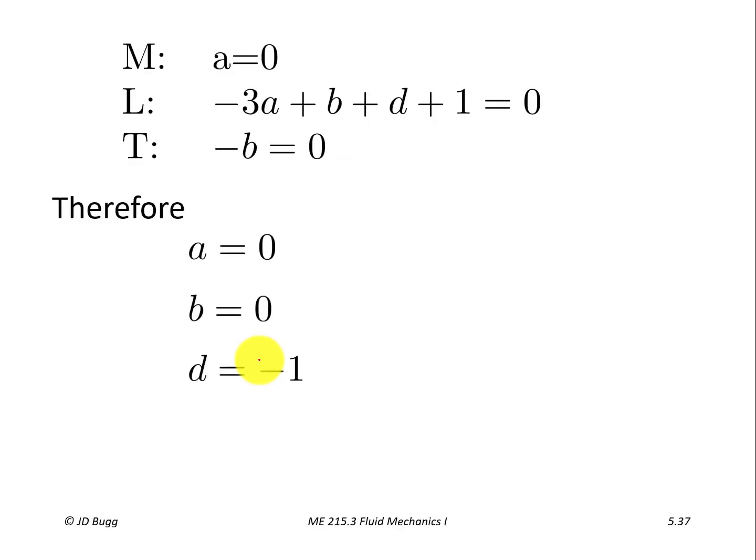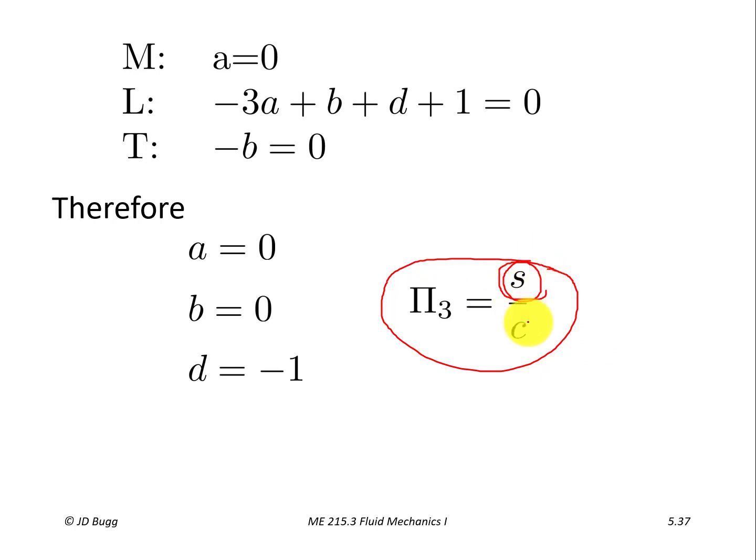So the resulting dimensionless group here, pi 3, is just a ratio of 2 dimensions. If we were to go on and add other physical parameters, other dimensions of this airfoil, like perhaps the curvature of the leading edge or the amount of camber, which is how much the whole airfoil is curved, if we were to add other descriptions of this airfoil that are described by a length of some kind, then the new dimensionless group that comes out would just be a ratio of that new parameter divided by the chord length. Because the dimensions of both of those are length, that would be a dimensionless group.